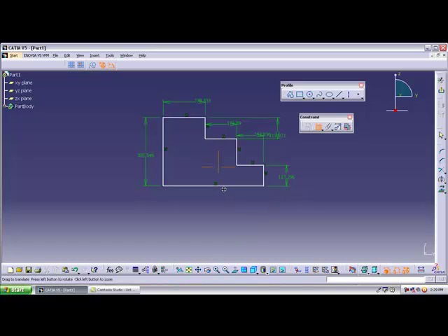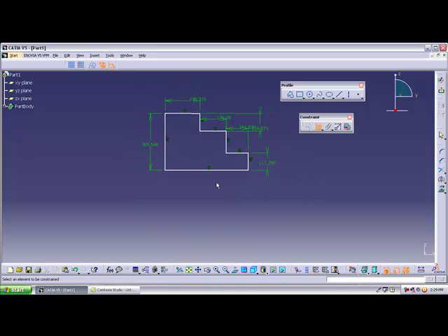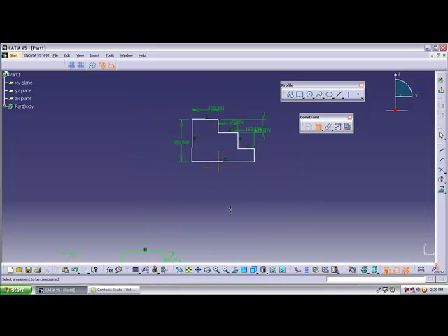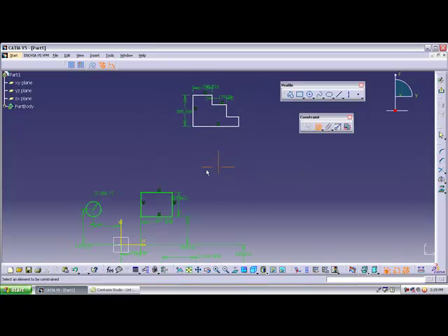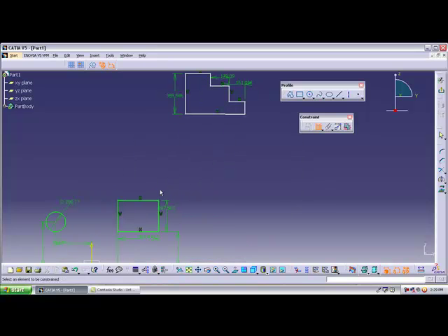So this is fully constrained. Right now we are giving the dimensions of the object. Is the object fully constrained now? No. Why? Because the object is somewhere in the plane, so we can give a dimension from the coordinate system. If we don't use the coordinate system, we can also use an adjacent object. Why do we give an adjacent object? Let me show. Suppose right now we give the dimensions from this object to this object. Now the object is fully constrained.